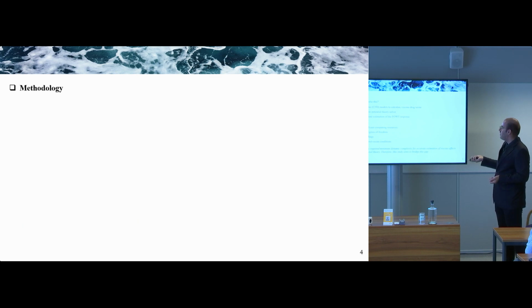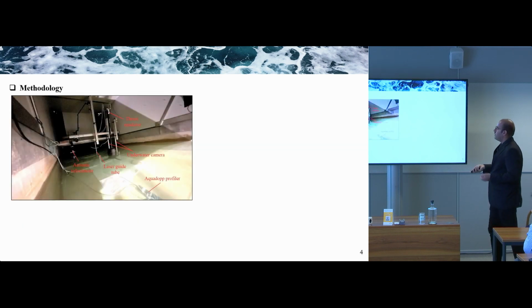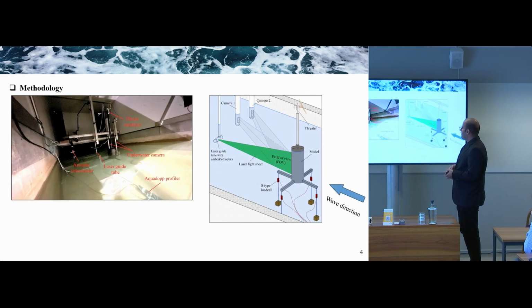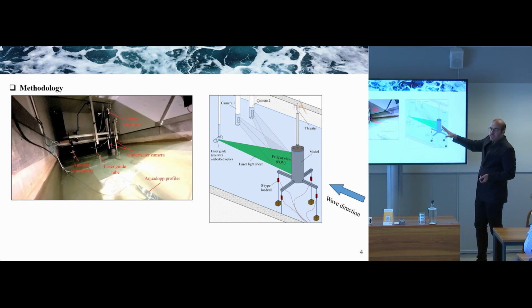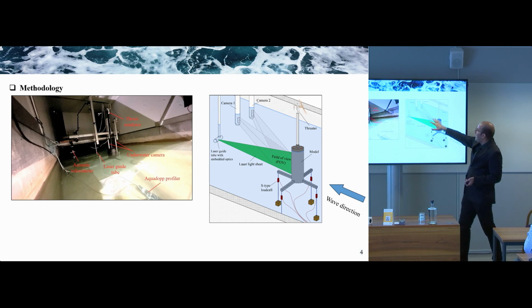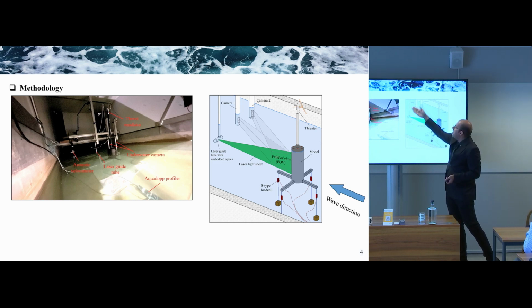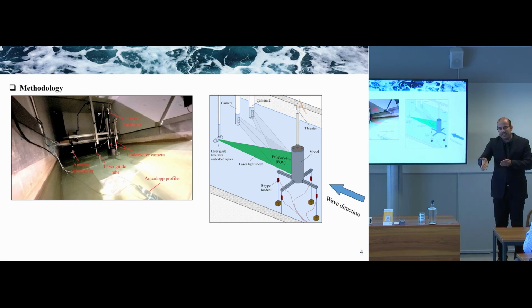And what I have done in part one was tank testing with the help of underwater particle image velocimetry. I'm just going to elaborate on the test setup really quickly. We had two underwater cameras and one laser guide arm, which through a set of mirrors guided the laser light to the underwater area. We have laser optics here, which create a light sheet when the laser passes through.